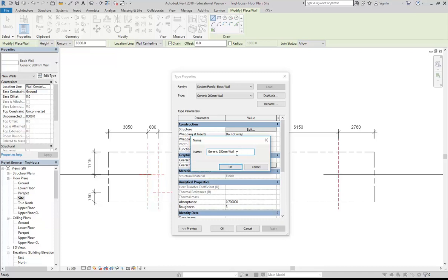If you're wondering why it's that size, it's because this is an old building. That's how I know it was probably 1870s or something like that, because it's solid brickwork. It's not even cavity. And that's the way the English migrants did the sort of construction they were used to over in Britain, where they didn't have cavities in that era, because the weather conditions weren't as severe as what you have here. And cavities were actually an Australian innovation, and then it spread back to Europe. So a lot of these buildings that don't have cavities, solid brickwork is how they're built. They leak like crazy. The water just goes straight through those walls.